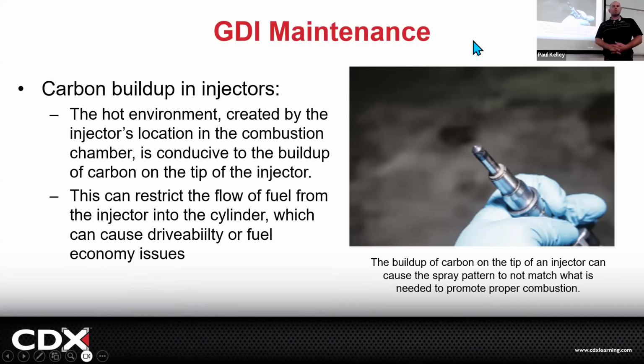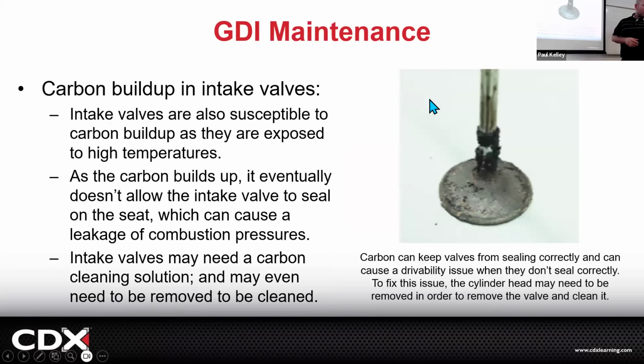All right, so one problem though. Carbon buildup is a major issue on these. So if you're not running that top tier fuel, and probably honestly, even if you are, we're going to tend to get carbon on the valves. You see how nasty that is? That's because back in the day, the port fuel injector would spray fuel and the fuel would kind of clean this. But now, because there's no injector in the port, all the fuel's being sprayed past the intake. When this intake valve opens up, there might be a little bit of leftover something and it kind of collects on the cold valve. It never gets cleaned. So we need to clean these periodically.